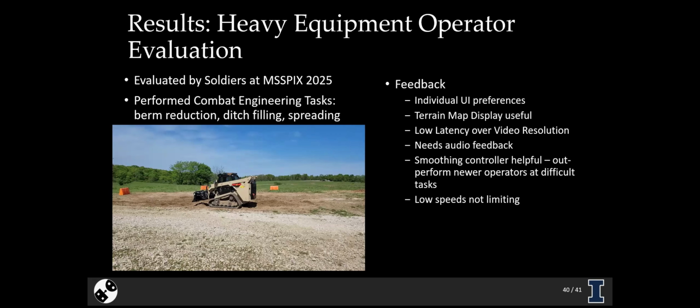They really preferred low latency over higher video resolutions, so we had to back those down because they wanted the video feeds to come in as least delayed as possible. Another thing they mentioned is they would really like audio feedback. This comes back to how operators use these pieces of equipment: sound is one of the other integral parts of this. You can hear when the blade touches the ground. You can hear when the engine revs up because the system is starting to stall.